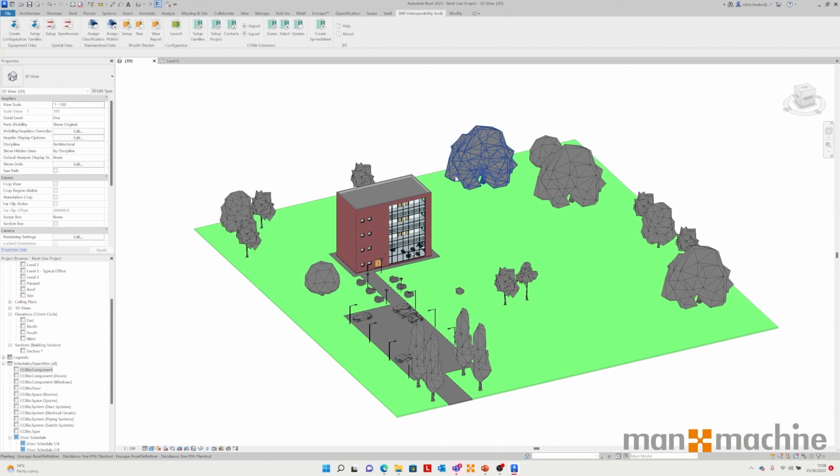But once we have that, it's attaching the relevant data that we need for building information modeling projects, whether they're IFC properties, COBie properties, classification properties, or just generic requirements that are set out within your AIRs, EIRs or BEPs. We've got the tools here that we need to add those properties and validate those properties. We can export COBie data, we can export IFCs, and customize to the nth degree any of those specific standards.